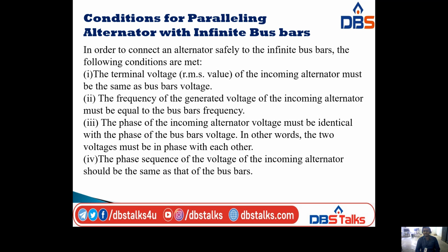The terminal voltage of the incoming alternator must be the same as the bus bar voltage. And the next one is the frequency of the generated voltage of the incoming alternator must be equal to the bus bar's frequency. And the third one, the phase of the incoming alternator voltage must be identical with the phase of the bus bar voltage.